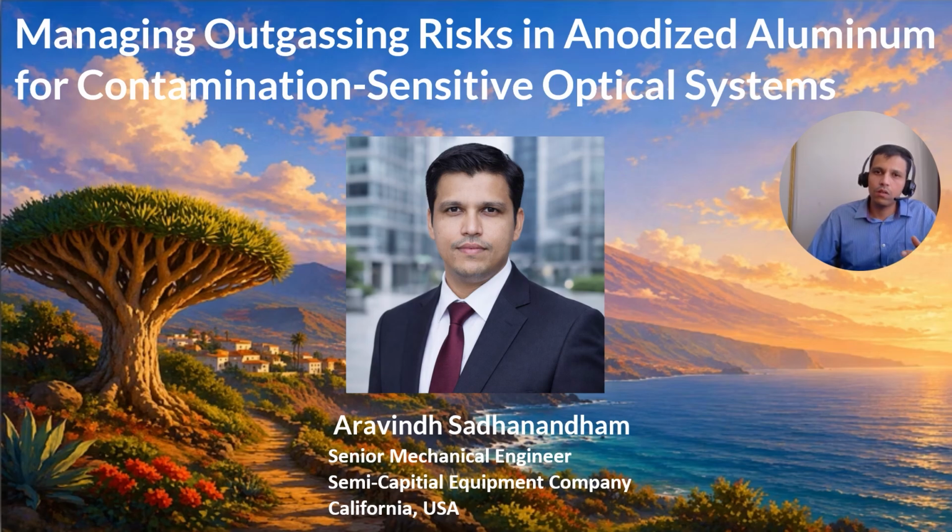And especially in these sensitive optic systems, even a single trace of a molecule on an optical surface will end up degrading the system performance, even causing yield loss on the wafer. Also, these molecular contaminations can generate haze formation on the optic surface.